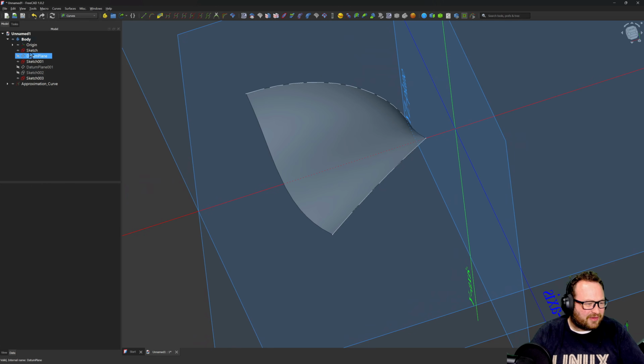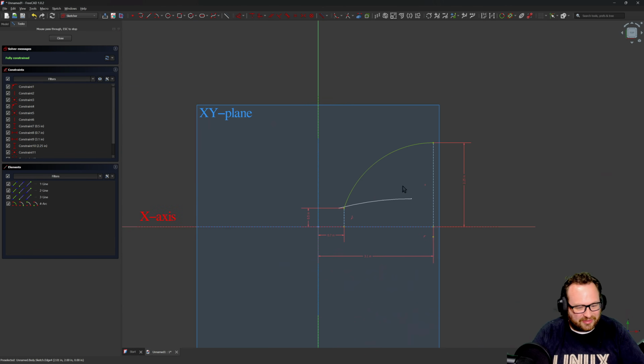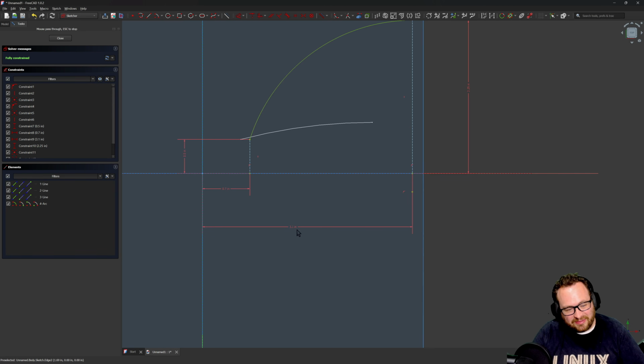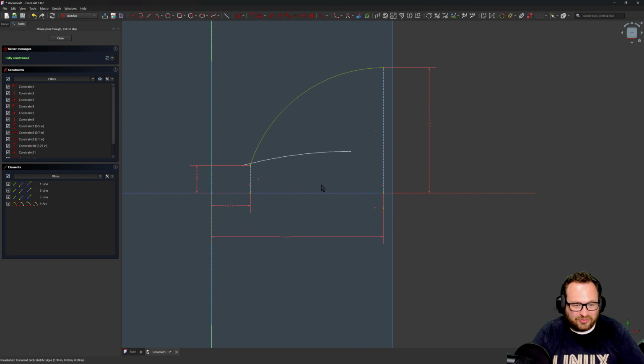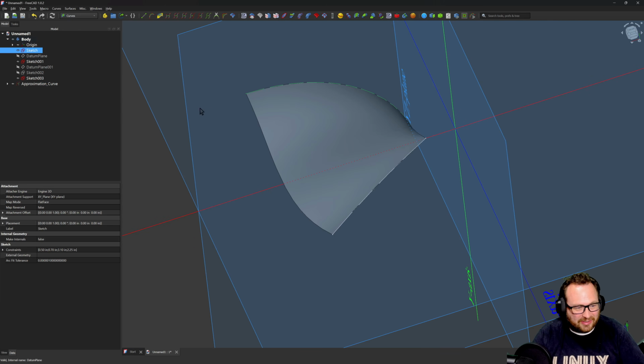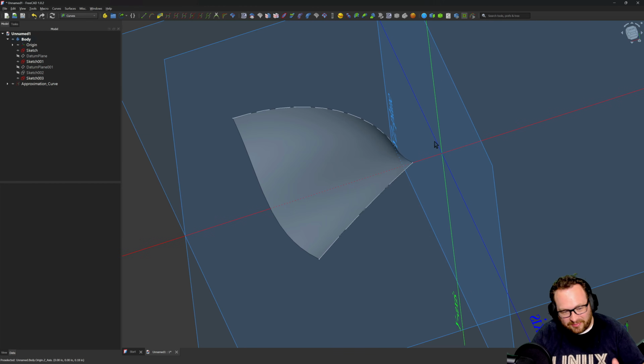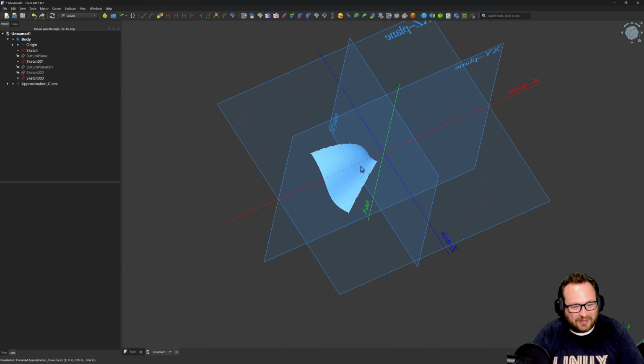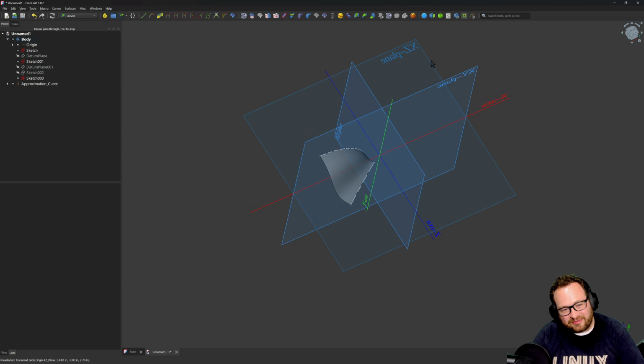Now we'll notice that if I go into, say, my original sketch, I made this 3.1 inches and 0.7 inches, right? These are just to give it a little bit of extra meat. My actual solid is going to be 3 inches and 0.75, so we're going to be a little bit within the surface, and that's so that we don't end up with a problem of something coming outside of the surface that we want. But now that I have a nice reference surface, I can create this XZ plane.